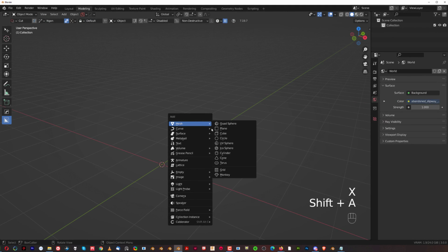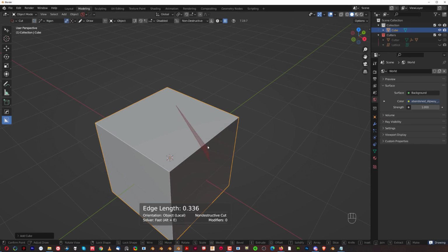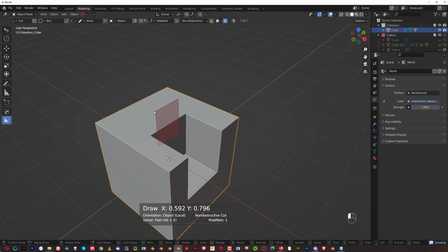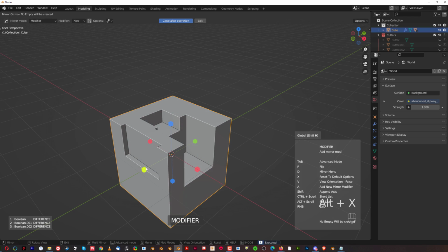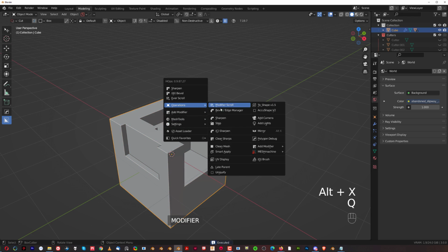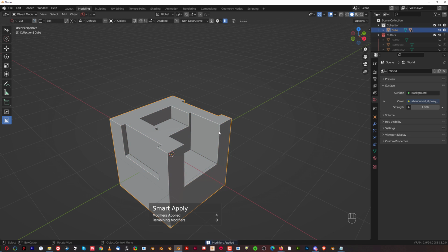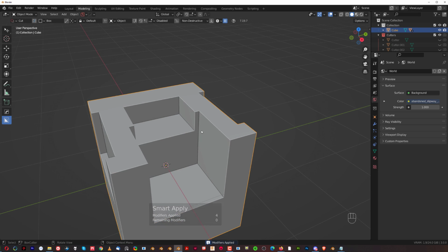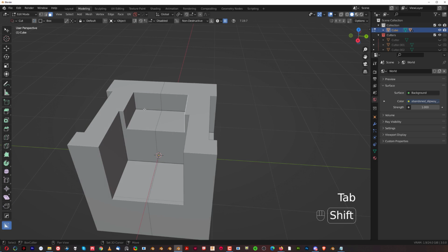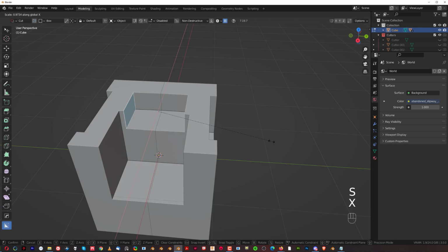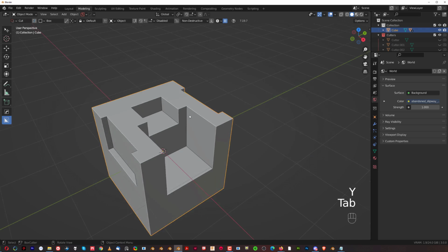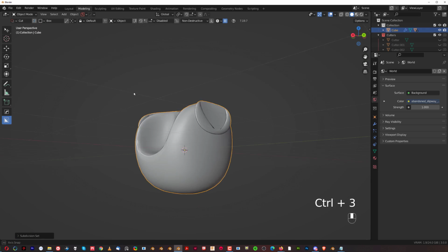All right. An amazing trick for very quick sub D on complex meshes is Bevel with HardOps. Let me show you. Okay, let me just create a cut in here. Let's create another cut in here, and maybe another cut in here. Okay, let's mirror this to the other side. Let's go to Operations and Multiply. And if I wanted to run sub D on this mesh, I'm going to be in a lot of pain, correct? Let's just make this a little bit smaller. Okay, there we go. If I wanted to run sub D on this one, I'm going to be in a lot of pain, right?